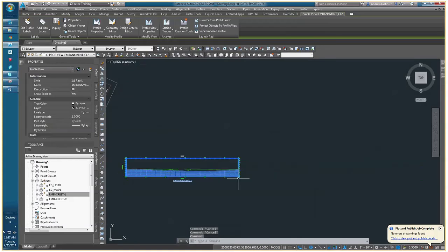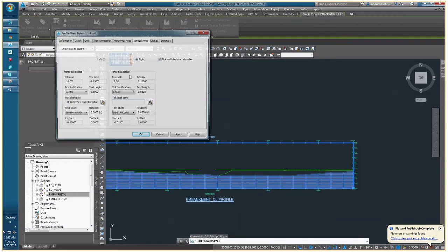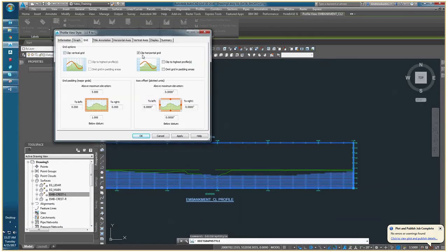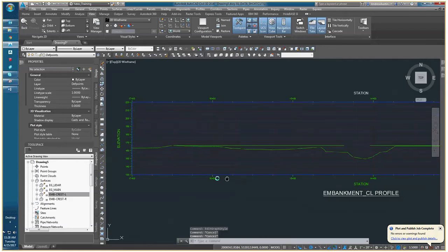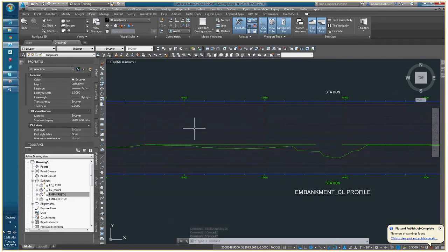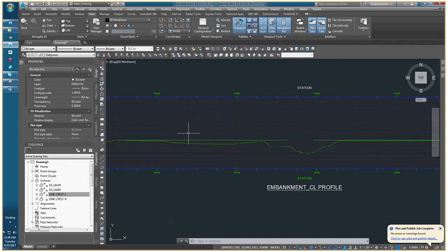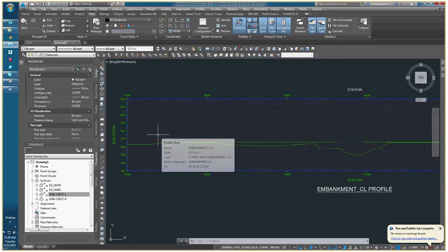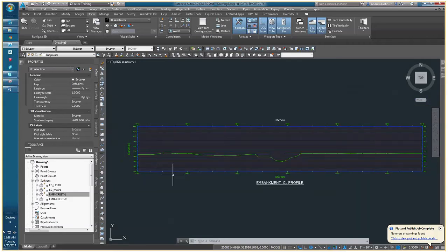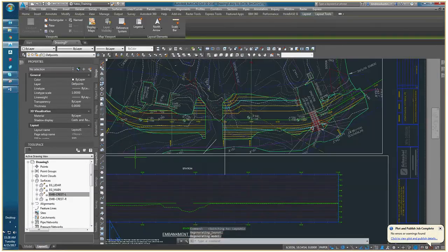Okay? Now, this is pretty important and is going to get back into some of these edits that we made earlier in terms of full grid. You'll notice that the stationing and the grid itself is quite different. We have these long grid lines in the left to right direction and these relatively short grid lines in the top to bottom direction. These can be edited in the profile view style as well. It can get a little bit tricky to mess with this stuff, and I'm not gonna mess with it right now too much.